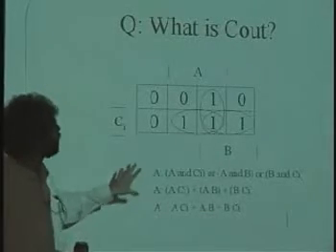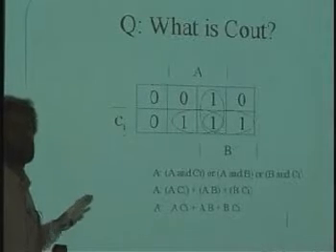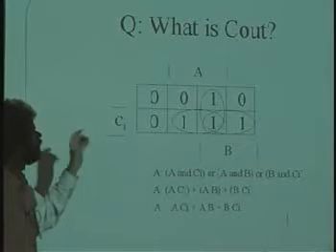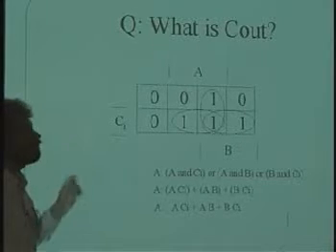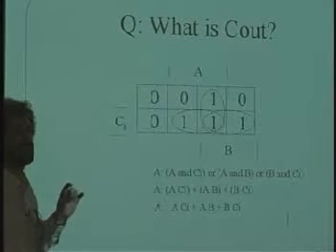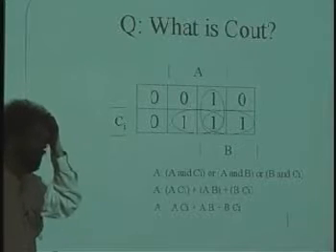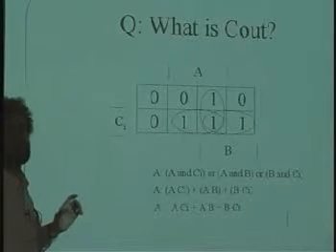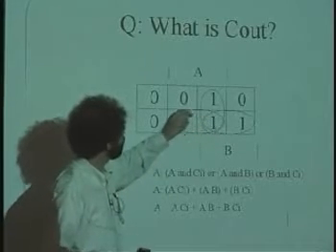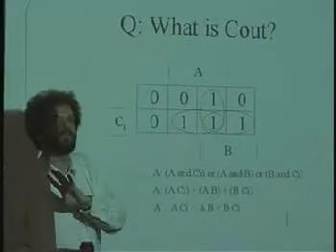What's wonderful is that this graphical technique allows you to simplify any sum of products form, anything where you have the OR of a bunch of ANDs, by coalescing smaller circles into bigger ones. Now there's a few rules. The first rule is you can't make bigger circles whose size, whose number of ones they enclose, is not a power of 2. Now why is that? Well, when I merge these two ones by changing it from a circle that's as big as a 1 to a circle that has 2 things in it, I eliminate one variable.